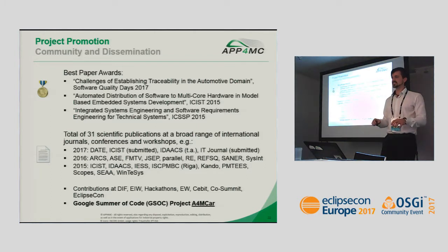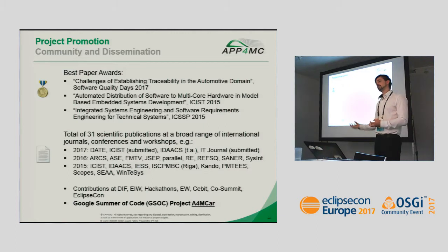It's an XMOS controller with 16 cores, so we had a little bit more flexibility in distributing the software, and also in defining constraints such that a very critical steering task, for example, runs on the real-time board and gets a dedicated core, in order to have execution times without much interruption.